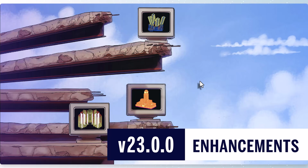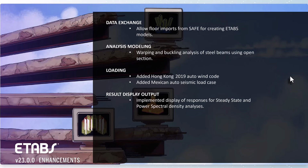In this video, we will be discussing the new enhancements in ETABS version 23.0.0. Here are the new enhancements. For data exchange, ETABS now allows floor imports directly from SAFE, creating new ETABS models, warping and buckling analysis of steel beams using open section. For loading, we've added the Hong Kong 2019 auto wind code as well as the Mexican auto seismic load case.